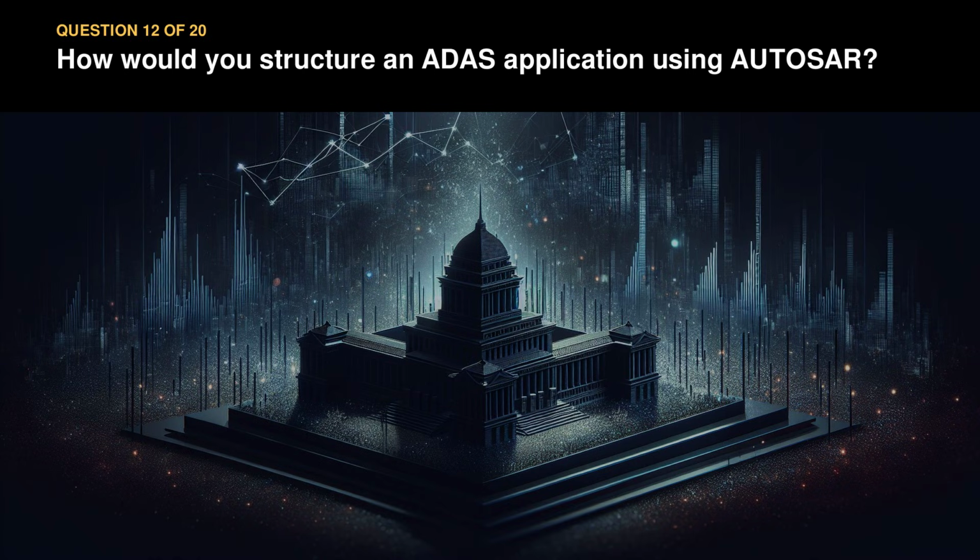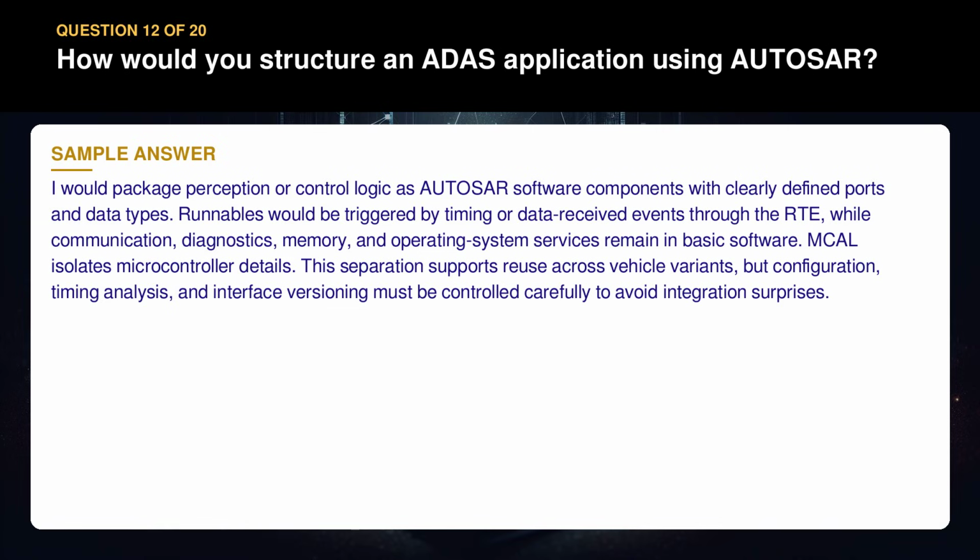Question 12. How would you structure an ADAS application using AUTOSAR? I would package perception or control logic as AUTOSAR software components with clearly defined ports and data types. Runnables would be triggered by timing or data received events through the RTE, while communication, diagnostics, memory, and operating system services remain in basic software.